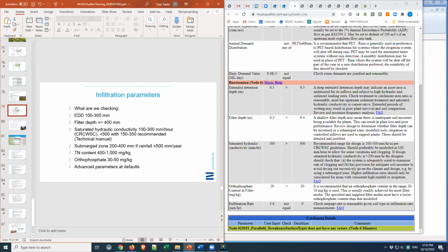It can take the form either of a surface infiltration basin, which might just be sand or gravel, and then it's just allowed to infiltrate to the surrounding soils, or it might be an underground infiltration trench or soakaway, which get used probably more in South Australia than most other jurisdictions. They've been adopted for a bit longer thanks to John Argue's influence.